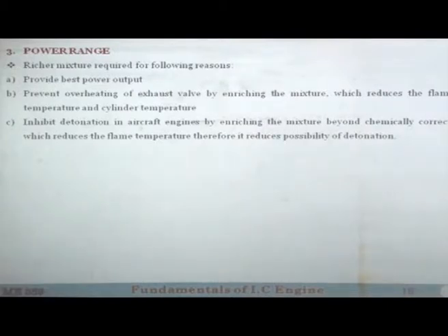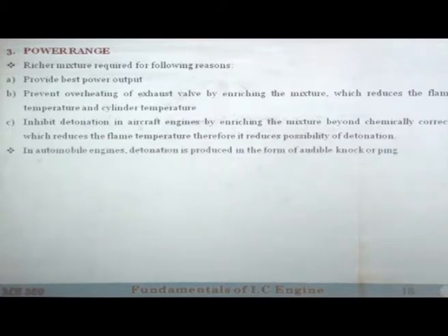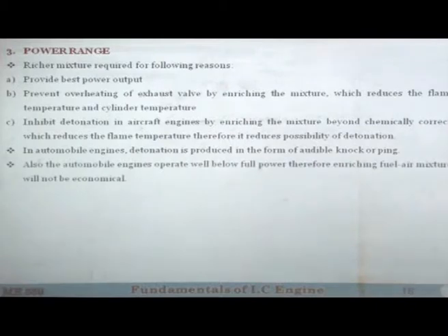When we are saying aircraft engines, we mean those based on spark ignition engines, not gas turbine engines, but gasoline-based aircraft engines. In automobile engines, detonation is produced in the form of an audible knock, but in aircraft engines there is no audible knock because they are already so loud. If there is a metallic pinging, it will be suppressed by the noise itself, so you will never come to know about it.